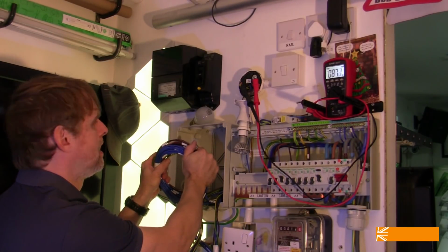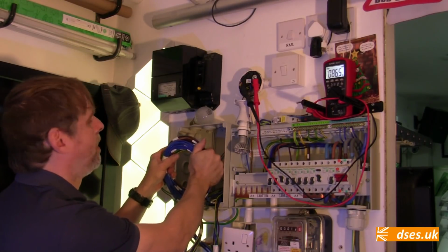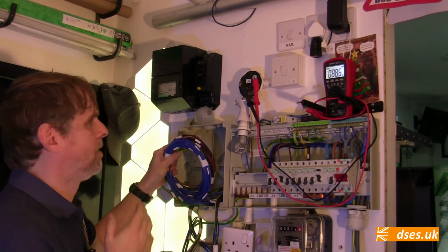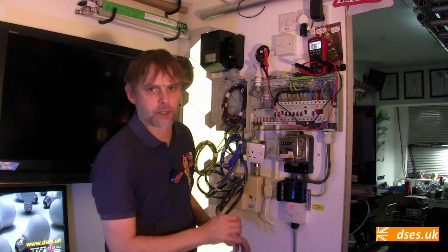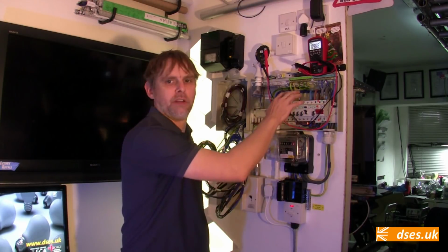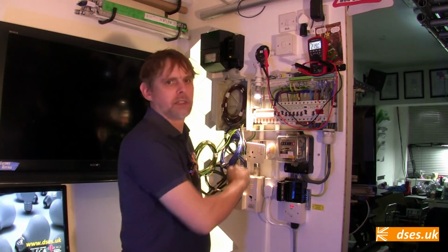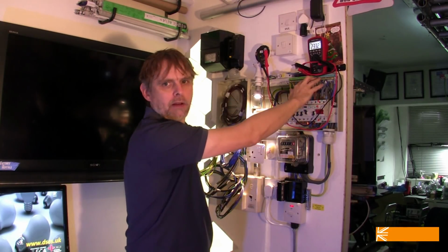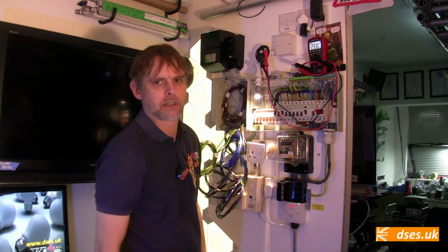But you can see that the electric field is diminished by the proximity of the circuit's neutral and CPC to the line wiring. Indeed, this setup is imitating a TNCS arrangement, so neutral and earth are connected together at the head. At the consumer unit, there's no potential difference between them. Even with a circuit energised and passing current, it's quite safe for me to touch between neutral and earth without any ill effects. The only difference between them, of course, is that the neutral is passing through the RCD.